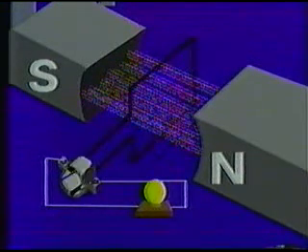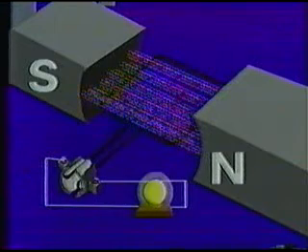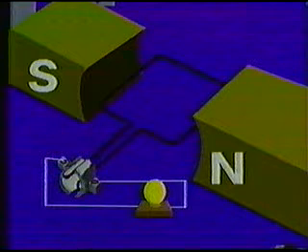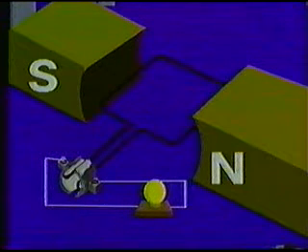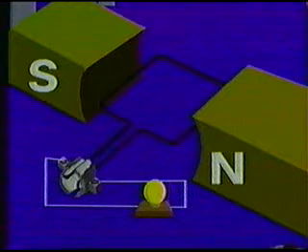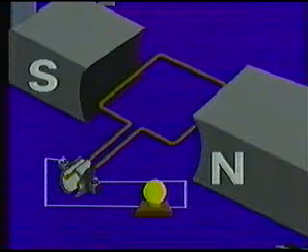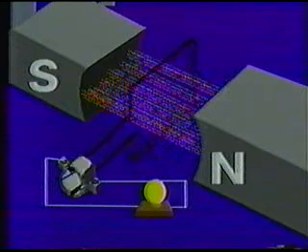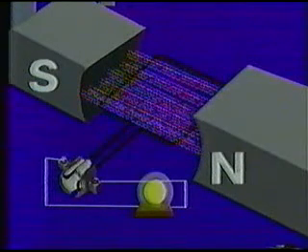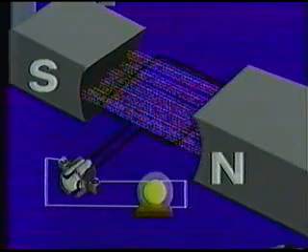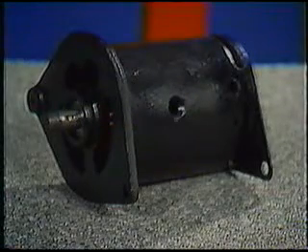But there are several problems shown here that make a device this simple impractical. First, using a permanent magnet to produce our field of magnetic flux is not workable. The weight would be enormous, and there is no way to vary the amount of flux that is produced by the magnet. Our conductor will only produce any electrical current once in an entire revolution. And we have no way to control the output of our simple generator, other than by how fast we rotate the conductor, or armature.